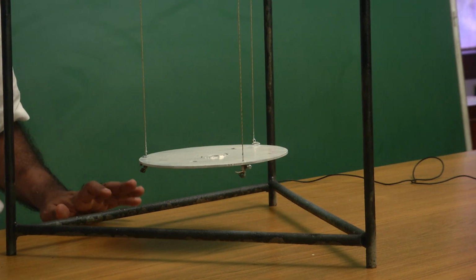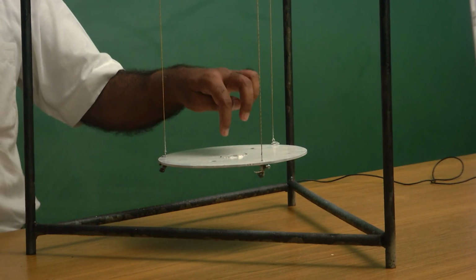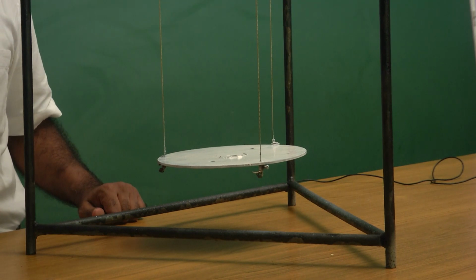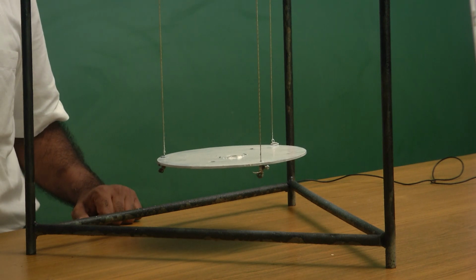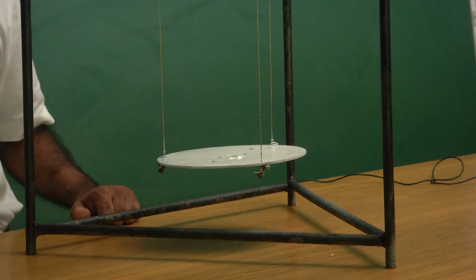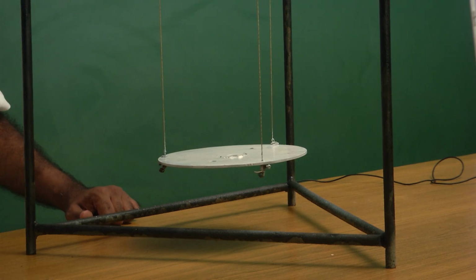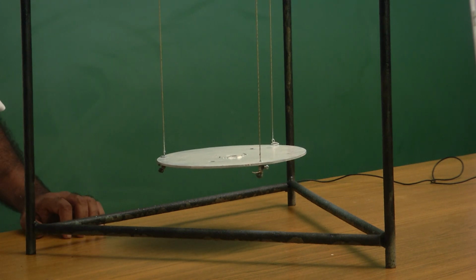So, that is how we find the mass moment of inertia of any body about a particular axis, which is not of a standard form and shape, as you can notice here. For standard objects, I mean the objects of standard shapes and sizes, we can find out the mass moment of inertia using simpler expressions known already, but for complex shapes experimental measurement is quite handy, and that is how this trifilar pendulum can be effectively used to find the mass moment of inertia.